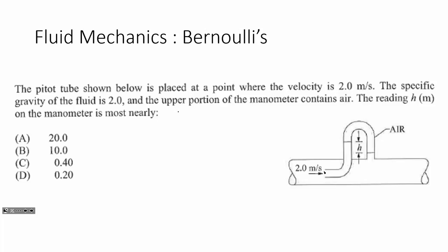Yes. Why is that? Frictional loss. So we can assume here that we can neglect frictional losses. So this is just a pure application of Bernoulli's where we assume that friction is negligible. Okay. So basically we can use that continuity principle here. We see that we don't have a change in area, so our Q in is going to be equal to our Q out. And since the area of this pipe isn't changing, that velocity has to remain constant throughout. Okay? Does that make sense?